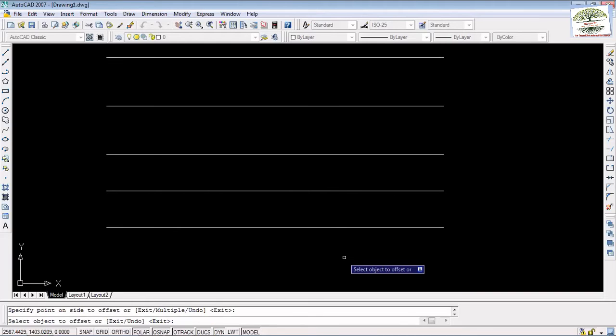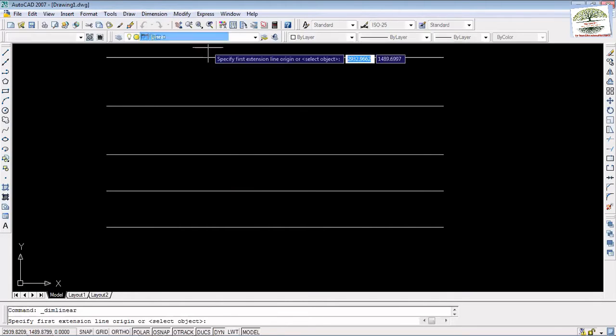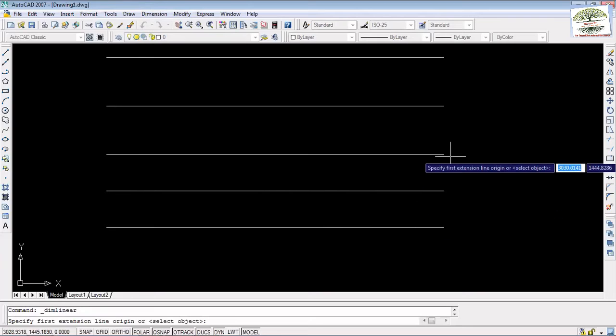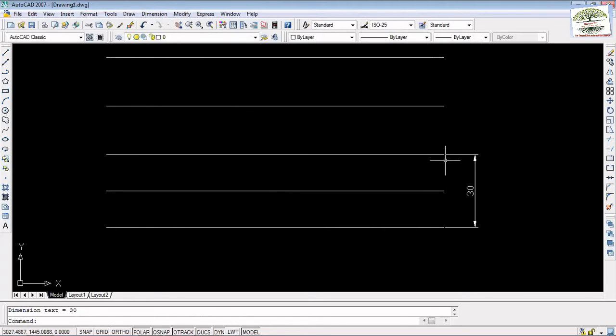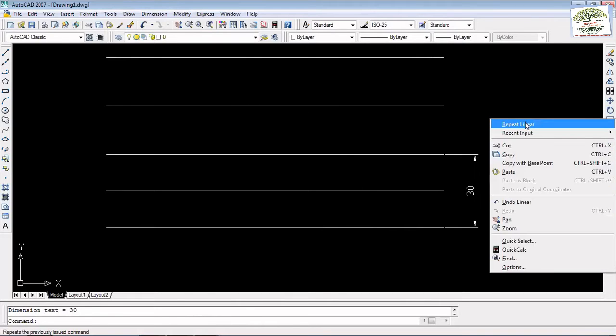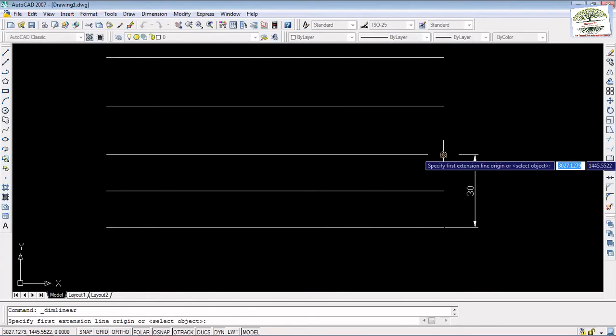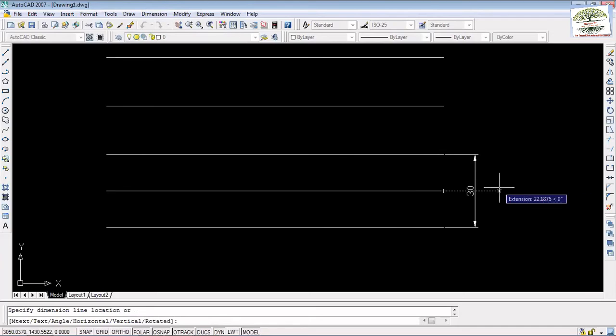15. So that's it. Now I have to discontinue the input sequence, so I pressed escape. Now the linear distance should come to 15 plus 15, which is 30. Okay, let's check 30. And now if I go for a repeat linear, okay, done. That's it.